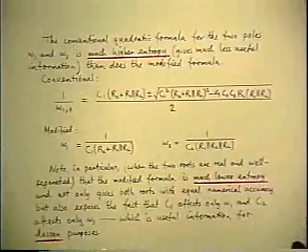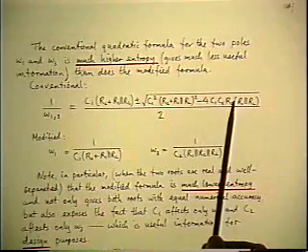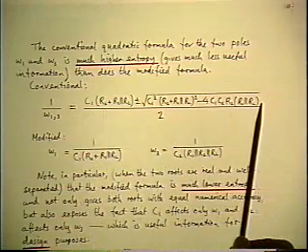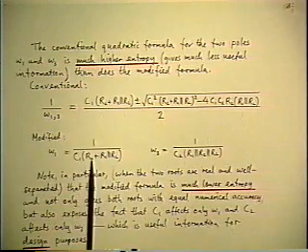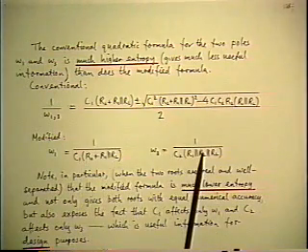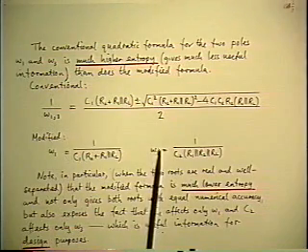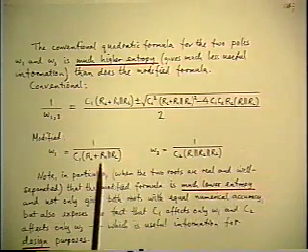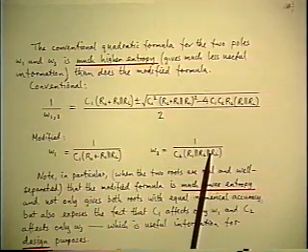So, again, to compare this result with the conventional one, and this is what we had in the introduction at the beginning, the conventional result is high entropy. The symbols don't tell you anything. The low entropy result shows you immediately that the two capacitors don't interact. C1 determines one corner, C2 determines the other. And in fact, there's almost no interaction between the resistances either, because R2 is negligible in omega 1, R2 dominates omega 3.